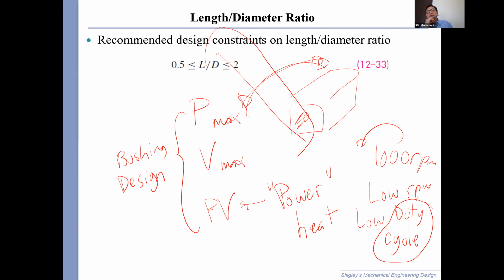Ball bearing, you need to be very accurate. Alignment, it's just a pain. Use bushing, and you will see later in your MSD projects, whenever you have movements, I want you to use bushings. You need to have a smooth sliding surface. Use bushings, and when you have high RPM, constant rotation, then use ball bearing. Okay, I think that's as far as I want to get with bushing.